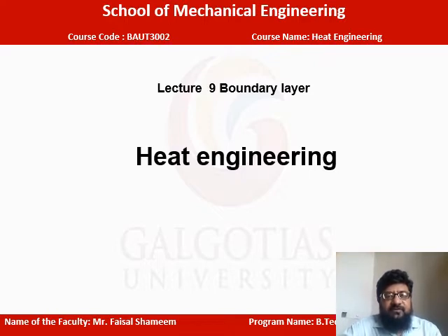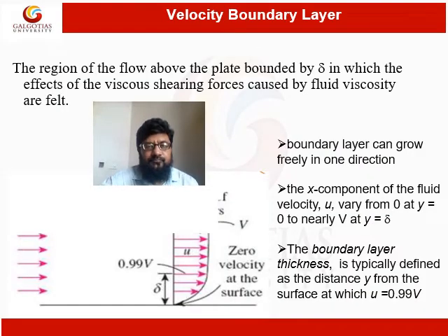In this lecture, we will study a very important concept of fluid mechanics, also relevant to heat transfer problems, that is boundary layer. So boundary layer is basically a thin region near the solid surface which influences the fluid mechanics and thus the heat transfer very much. So let us first talk about velocity boundary layer, or it is also known as hydrodynamic boundary layer.